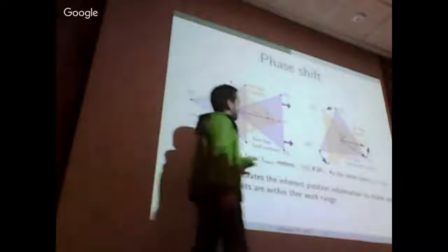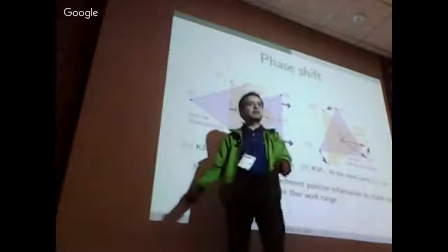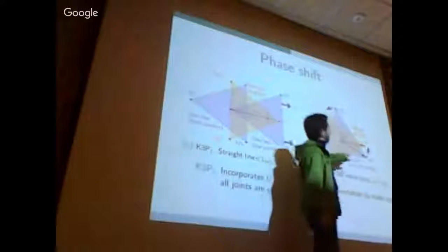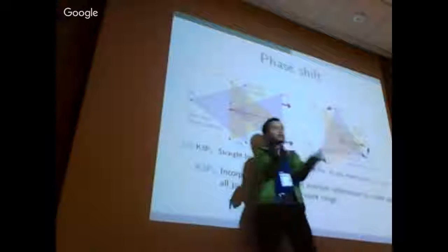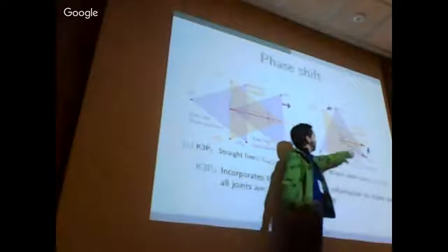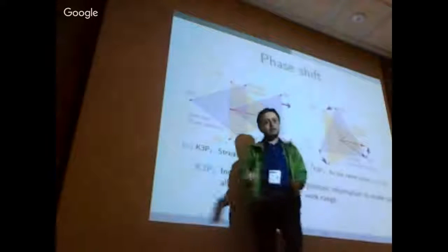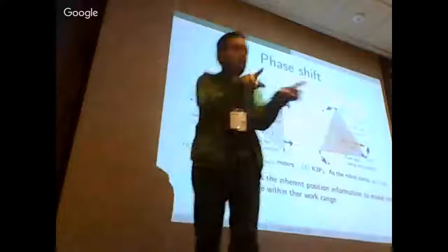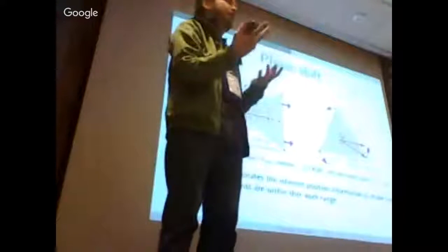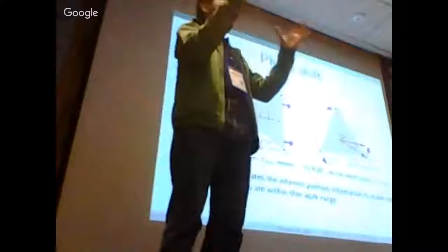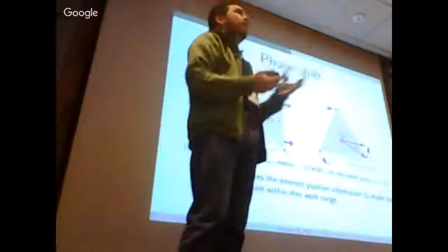And the other is when the robot is turning, two limbs may get too close to each other. I will show you this angle. If they get too close to each other, then a phase shift is triggered so that the swing tripod lands, and the other tripod supporting the vehicle can take over and move to continue the turning motion